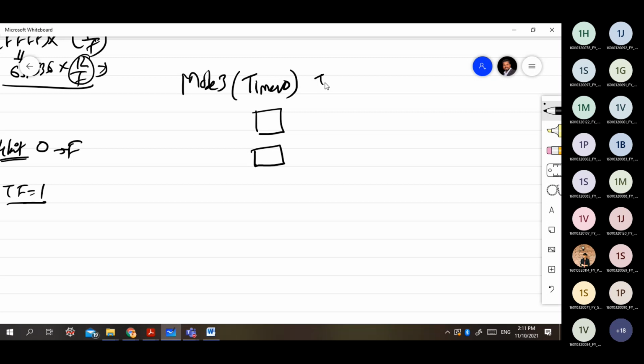Okay. So in timer 0 we know we are having TL0 and TH0. So we can use TL0 for a separate count and TH0 for a separate count. Meaning we can give a different frequency to this one and a different frequency to that one. Getting it? Whenever this overflows, that will be indicated by TF0, but whenever this overflows, that will be indicated by TF1. Understand, now there will be two separate 8-bit counters.